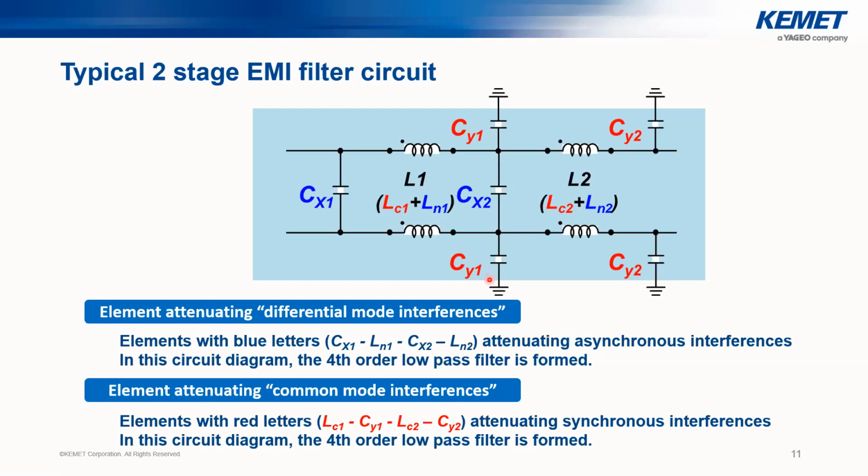This noise is then synchronously distributed across all your line and neutral planes, which is why it is also called common mode noise, because it's really common to all the AC mains line signals supplying your device. Asynchronous noise affects individual lines or the neutral line, which is why it is called asynchronous mode noise.